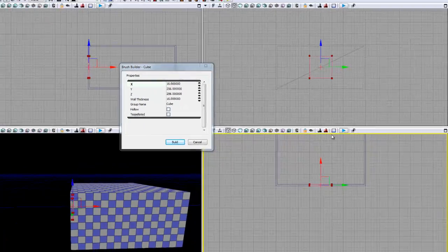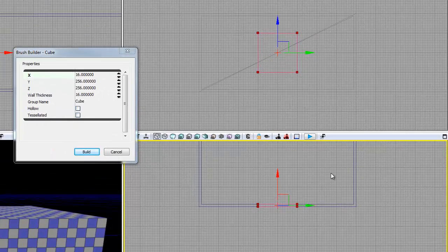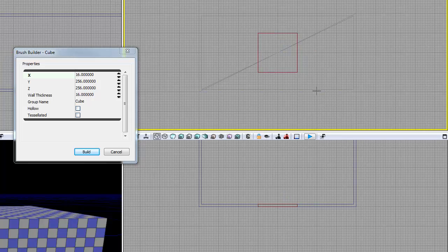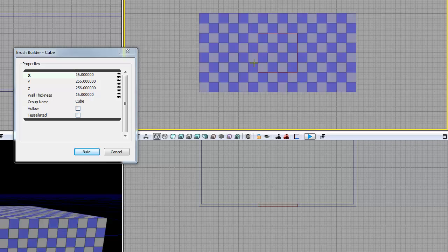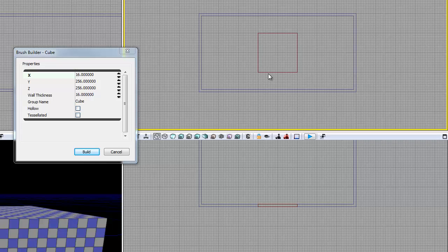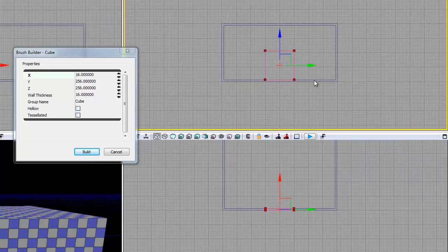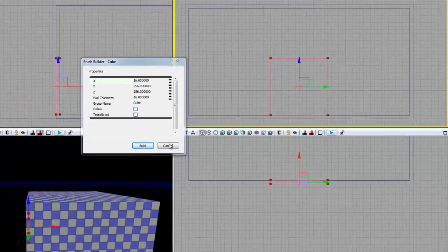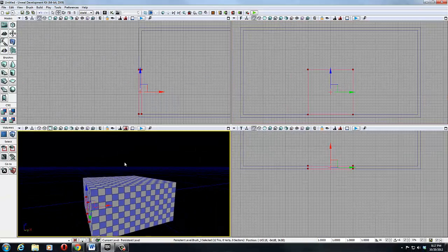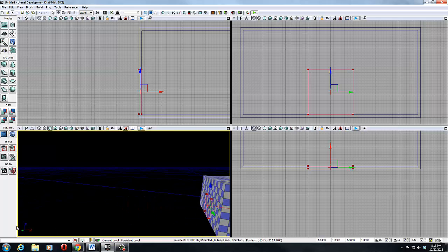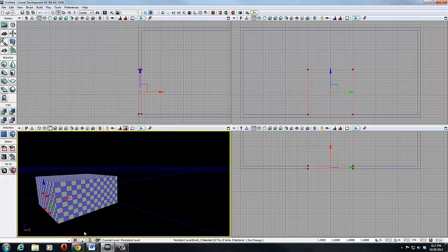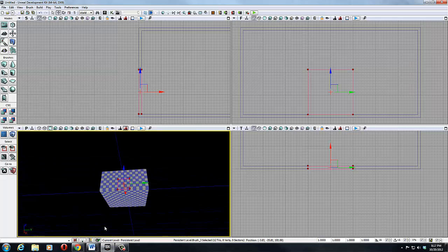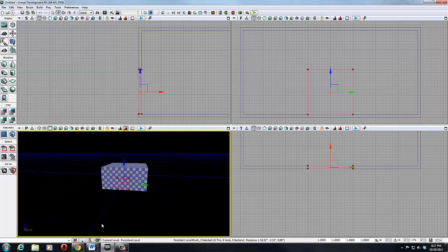So you can see now I was able to get it lined up, and if I look at my front view, I can actually grab my door and drag it down. You can see that it's sitting right on the floor, and in the top view it's lined up where that's at. Now I'm going to make sure I turn my perspective view around so we can see this happen. And remember, you can always hit the L key and it will orbit around your selection.